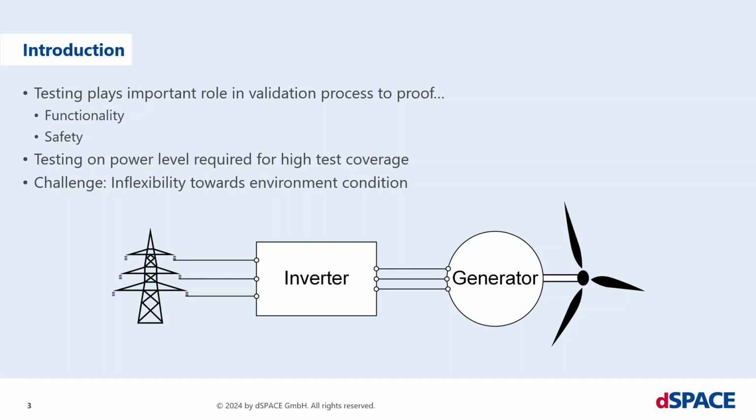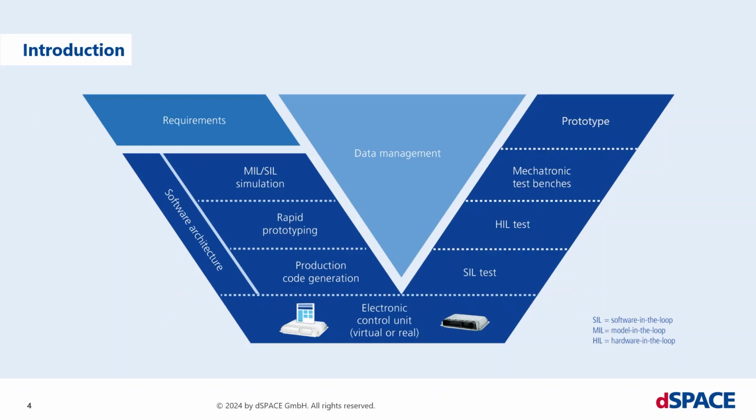To give you an overview of which test methods are available in general, I want to take this slide with the common V-cycle. Hopefully everybody of you knows this V-cycle with the development path on the left-hand side, and we have the validation path on the right-hand side. The test coverage on the right-hand side increases bottom up, so we start with software in the loop testing, which is mainly based on simulation tools. So your device under test is simulated in a fully virtual environment.